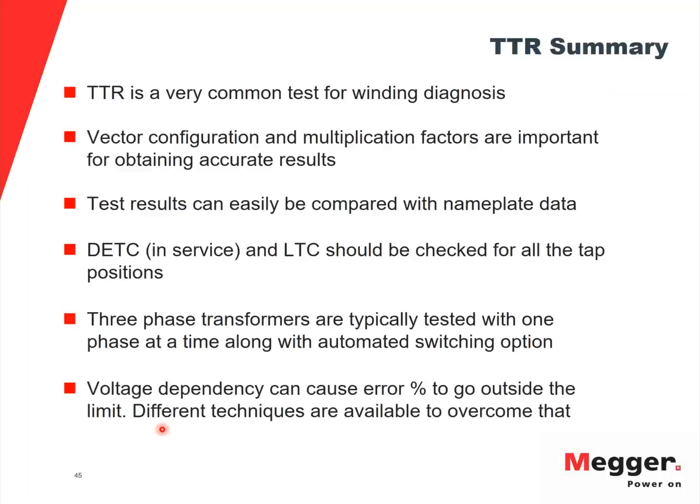To summarize, TTR is a very common test. You need to be careful about the vector configuration and your nameplate information. The reason why this test is a preferred test is that it's an on-spot diagnosis where you can compare the results with the nameplate data.